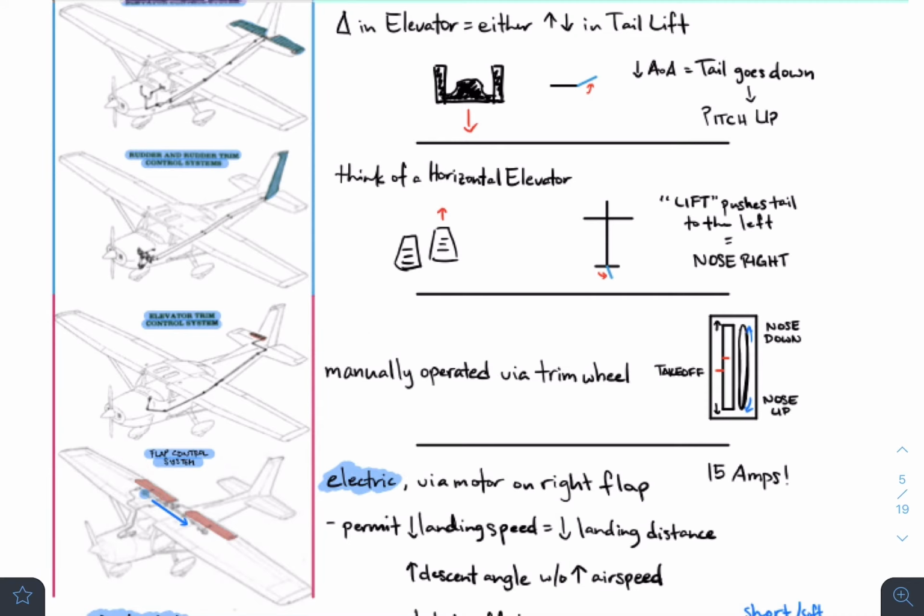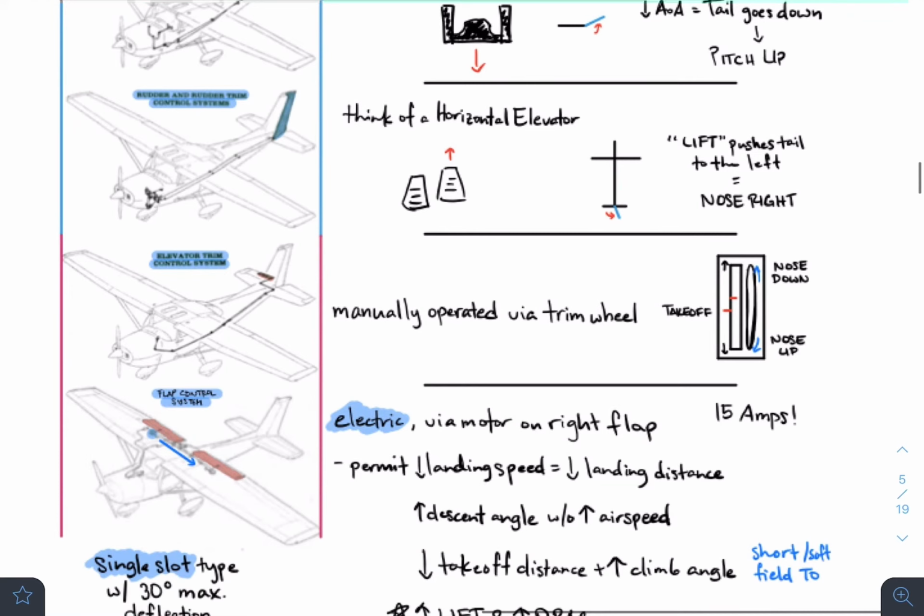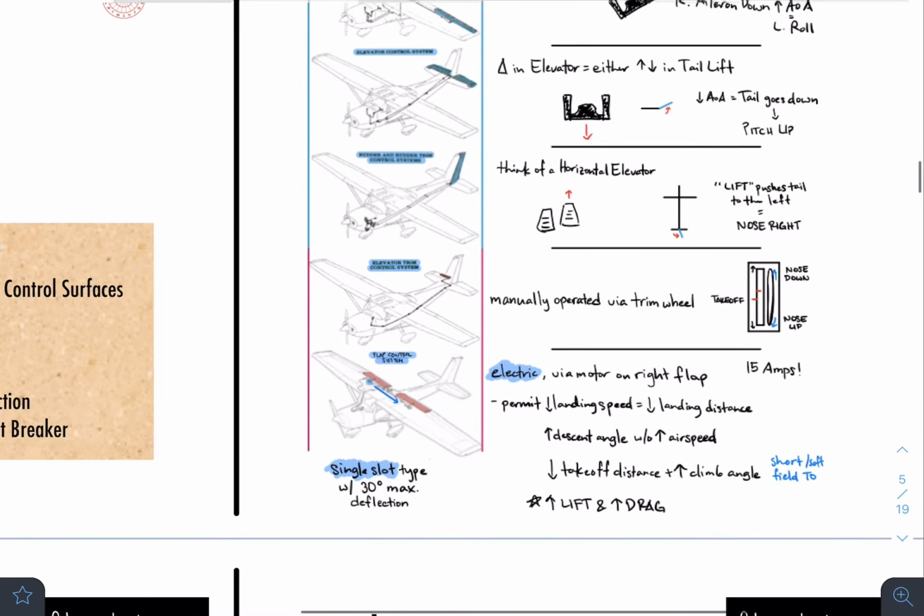Because if you take off with a certain amount of trim already, you could be taking off with a trim like this or like that over by the tail, and that's just going to affect the rest of the way you fly. So just make sure you keep in mind to standardize the trim or set the trim up during your pre-flight. So that would be the secondary.